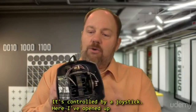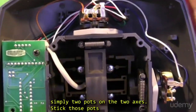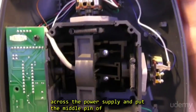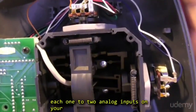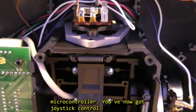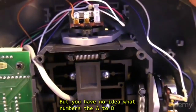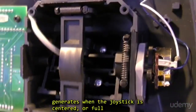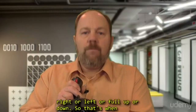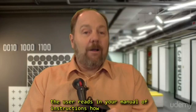Now here I've opened up this joystick so you can see how it works. It's simply 2 pots on the 2 axes. Stick those pots across the power supply and put the middle pin of each one to 2 analog inputs on your microcontroller. You've now got joystick control. But you have no idea what numbers the analog to digital generates when the joystick is centered, or full right or left or full up or down. So that's when the user reads your manual of instructions on how to calibrate.